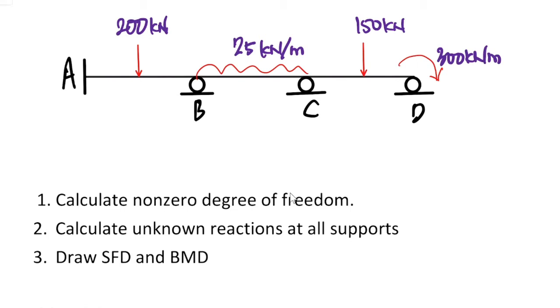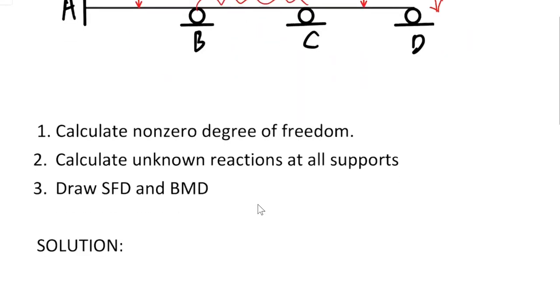What we need to do is: number 1, calculate non-zero degree of freedom. Number 2, calculate unknown reactions at all supports. And number 3, we need to draw shear force diagram and bending moment diagram. Okay, so we will start this.